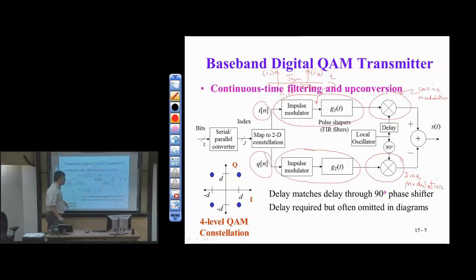Now, in discrete time, this is pretty easy to do because we can generate cosines and sines separately very easily. We did this in Lab 2. We also covered it in Lecture 1: difference equation, lookup table, math library call. Pretty easy to generate cosine and sine separately and keep them 90 degrees out of phase. We don't have to have a single oscillating source and then split that into two signals, cosine and sine. In some cases, this is what we have, for a lower cost oscillator.